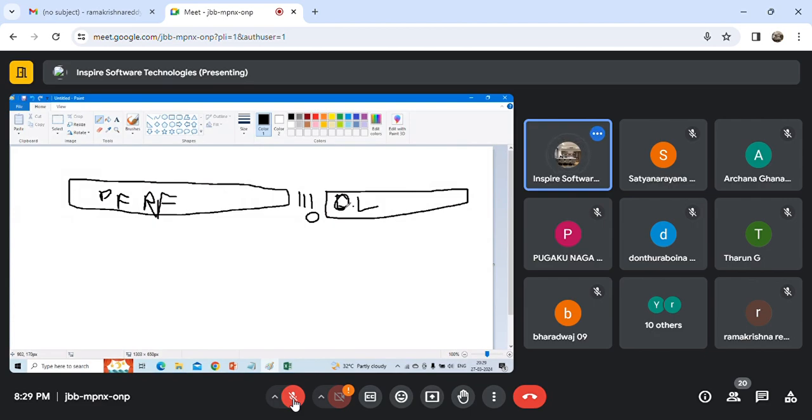Is it clear? When a receiver intentionally wants to wait for some time before the transmitter sends another message, it can send the overload frame. Or if any of the nodes sees a dominant bit in the interframe space instead of the recessive bit, in any position, either here or here or here, anywhere, then also the overload frame will be sent.